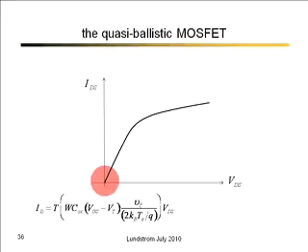We have our expression for the ballistic MOSFET under low drain bias. Let's just multiply it by T. In fact, we could compare the measured characteristic to this theoretical expression, and we would deduce from the data I showed you earlier that T is 0.2. 20% of the electrons go across ballistically.